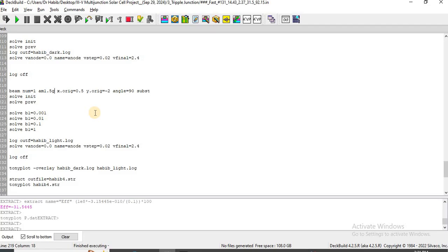Now, what is AM 1.5? Basically, the path length of light in the atmosphere depends on the angle, which will vary with the time of the day. This is given by AM, air mass, or you can call it the air mass number, which is the secant of the angle between the sun and the zenith, or you can say between the sun and the vertical angle. So AM0 would represent the solar spectrum outside the Earth's atmosphere. Similarly, AM1, which we see when the angle is 0.